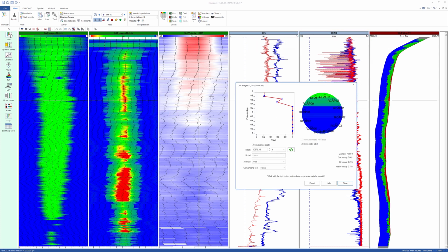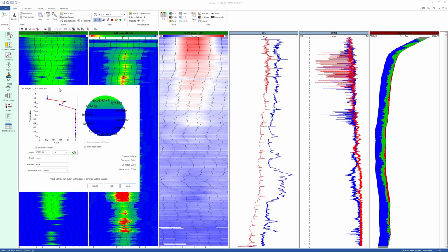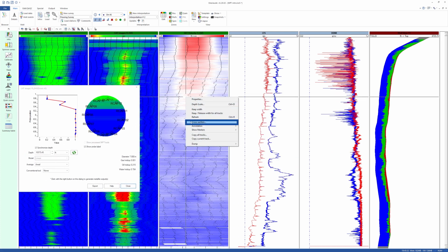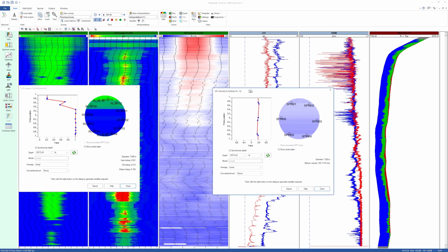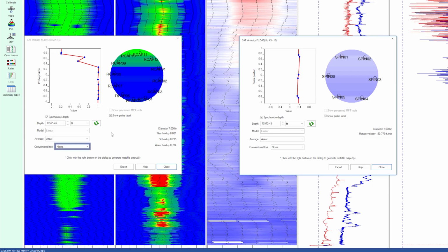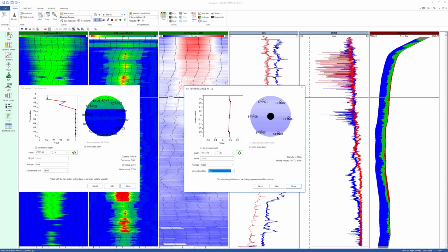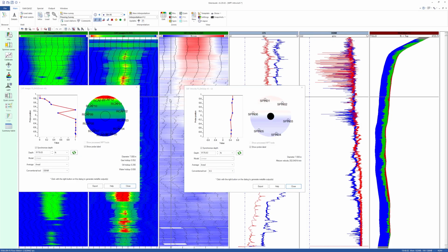The cross-section reveals that the flow is stratified, with the lighter phase flowing faster towards the top of the tubing. By displaying the location of the centralized density and velocity measurements in the cross-section, it is clear that these are not measuring representative cross-sectional velocities or holdups, which are necessary for conventional multi-phase profiling using correlations.